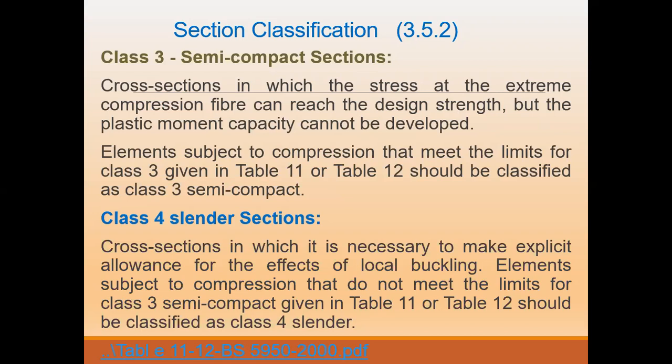But while the design strength is reached, the full moment capacity cannot be developed. So they can withstand sufficient compression stresses, but they cannot reach the plastic moment capacity. That means no plastic hinge is formed when the section is subjected to loads.